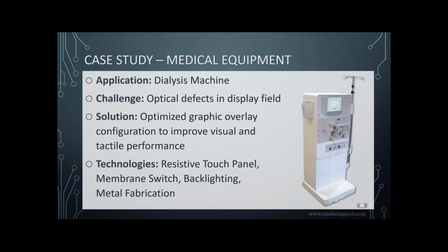And sometimes there are byproducts of needing to go with a large panel. In this case, we chose a resistive touch panel because, as dialysis implies, there's blood and fluids in the environment. So the device needs to be cleanable, needs to be wiped down. And that's why we went with the contiguous first surface of that. As I say that, I recognize that we need to be very clean, and yet somewhere on the red button there shows some staining going on there on the stock photo.